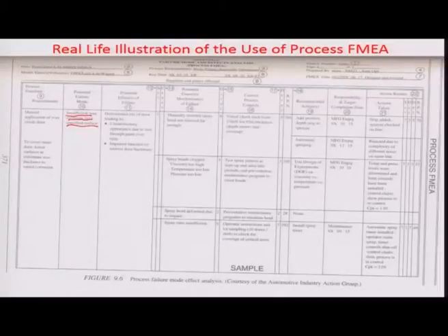Generally, if I look at how a door of an automotive would look, so if I remove, let us say, the door standalone, and if I wanted to investigate the door by looking at a cross section of this door, you may find that after removing all the trim boards, etc., which are there within the passenger cabin, the door looks like a structural hollow with some ribbed members on the inner side and an outer member which is a metal sheet on the outside, and it has the curls and curves of the overall automotive.